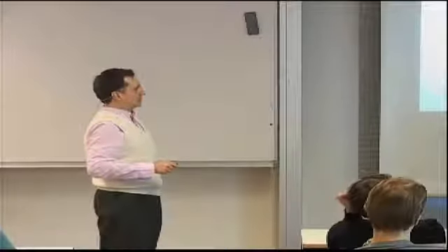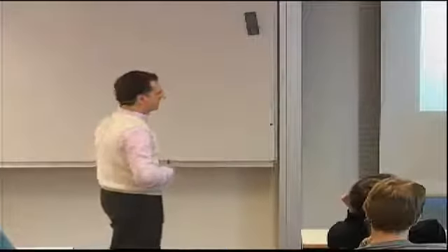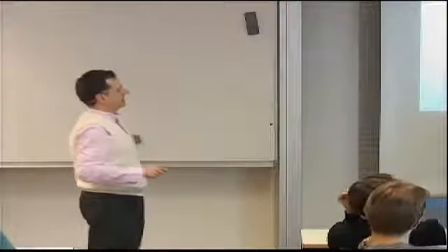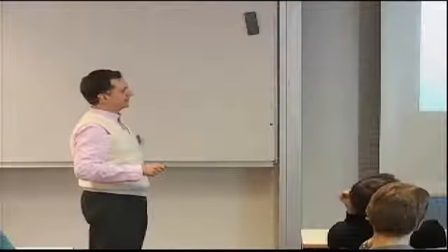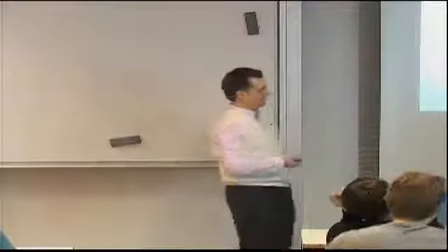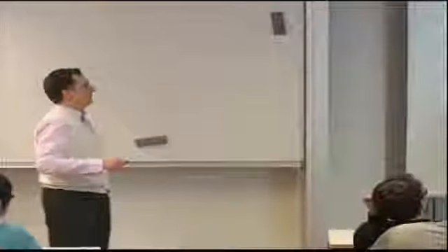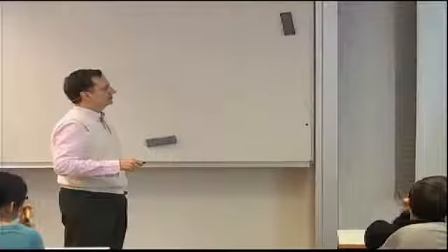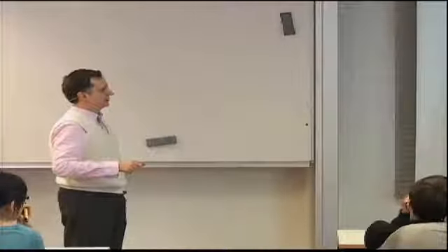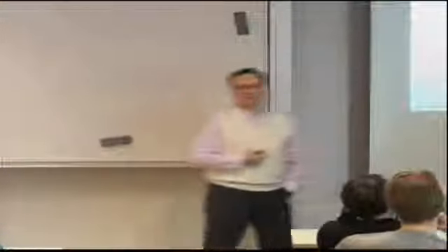We have exactly the same thickness for 2 different layups. One has 2 45s and 3 zeros in the middle. The other one has the exact same plies, but now they're stacked differently: the zeros are on the outside, 1 in the middle. So in both cases, these are symmetric. They have the same thickness, the same types of plies, only the stacking sequence changes. We are supposed to determine the highest Nx value when this load is applied and its location, and then see which of the layups, on the basis of this, is the best layup.